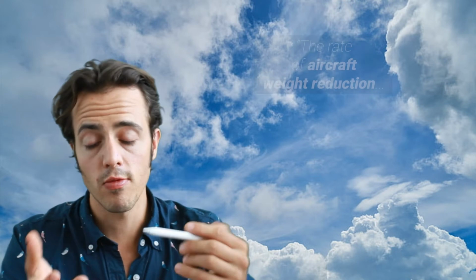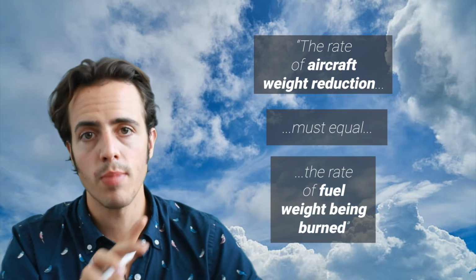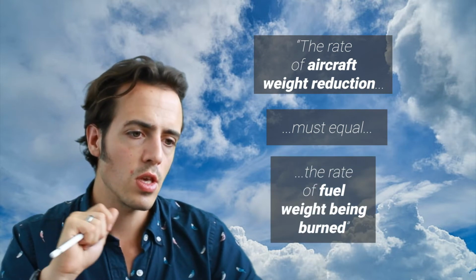And fundamentally, the problem is distilled into what I called the Breguet range equation. This was first developed for propeller aircraft. It was developed by someone else who wasn't actually Breguet, but we can use it to help us develop the gross still air range, and we can distill it down to the fundamental concept, which is that the rate of aircraft weight reduction is equal to the rate that the fuel is burned in terms of weight. So we're going to use that to develop these relationships, and we're going to do it slightly differently for turbojets and for propeller-powered aircraft. So let's move over to the whiteboard now.